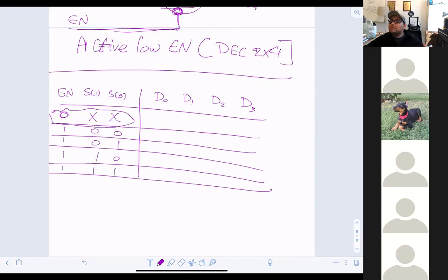D2, D3, it depends on what you want as a designer, right? If you are seeking low power, make it 0. Somebody else will tell me that in some circuits, if I put X, it will be low power. You know why? Because then the K-map will do what? It will make more optimization, then fewer resources will be used. Okay?